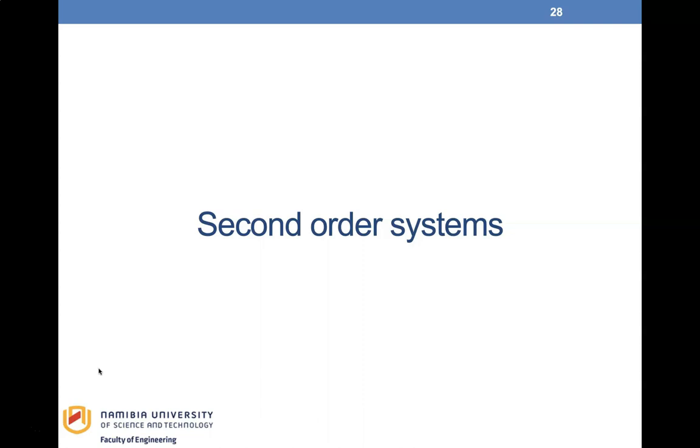We observe that changes in the first order system parameters will only change the response speed of the system. However, changes in the parameters of a second order system will change the form of the response. Second order systems could exhibit a damped or pure oscillation for their transient response.